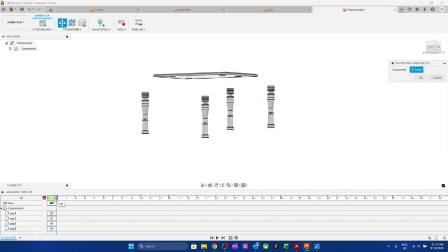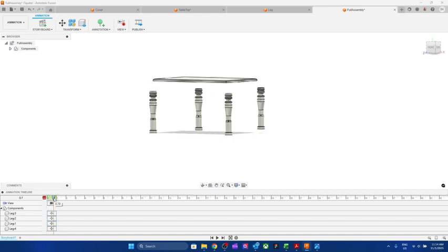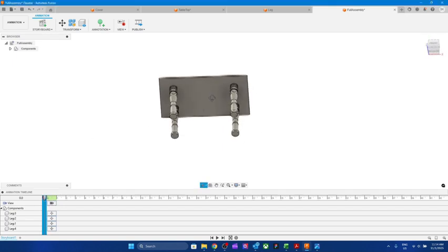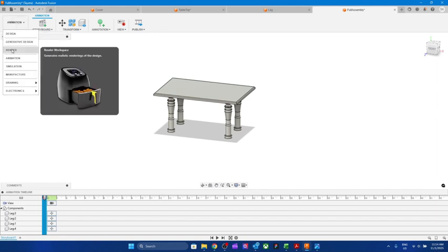And now you can see if I change, click OK, sorry. So I can assemble, disassemble, and so on. Okay, exploded. So that's how you create the exploded view. I think I should stop here to give you a chance to digest what we have learned.